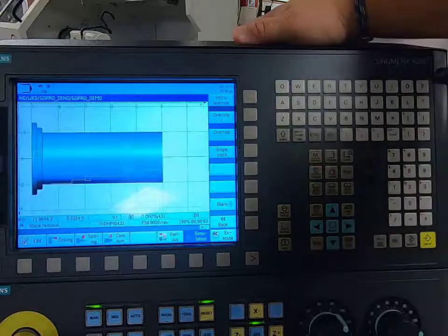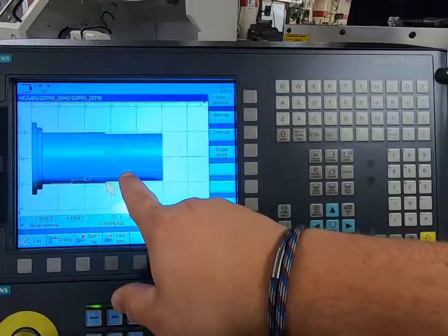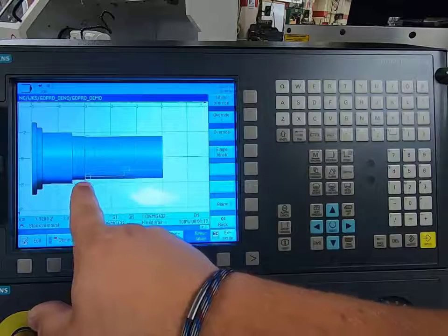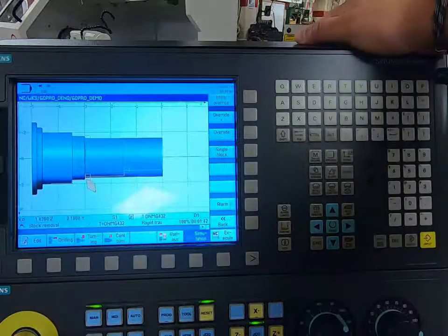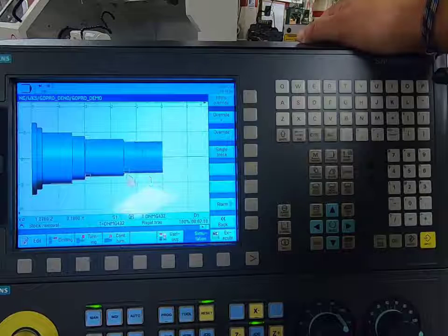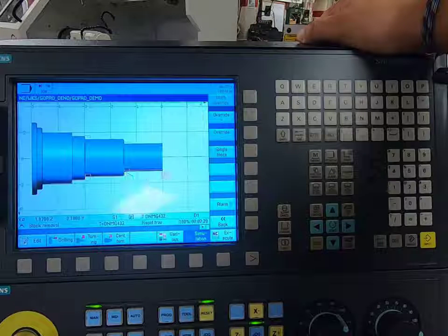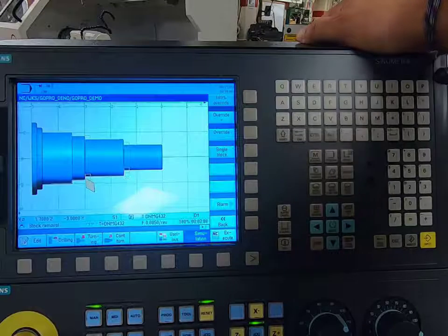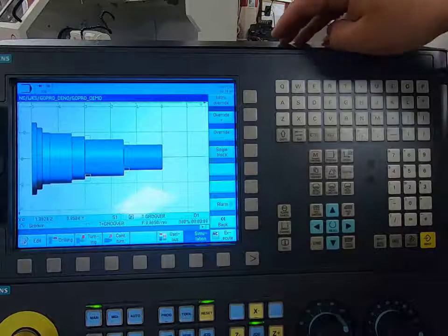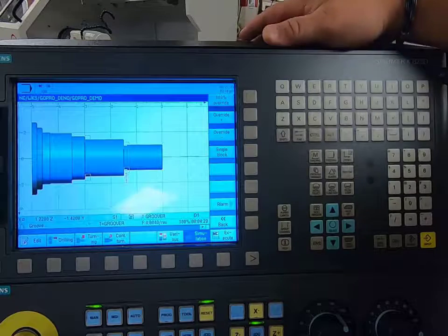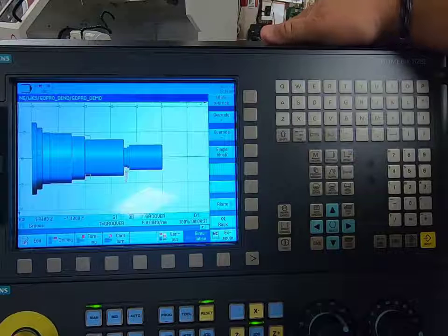So if you look there, my grooving tool is a little bit further in on the shoulder, whereas this one is out past that diameter, so the side of my tool will not run into the face of that shoulder, okay? Now keep in mind, it will cut air for a minute or two. That's not a problem, okay? I say a minute or two, I'm exaggerating. It'll just take maybe about another 10 seconds, okay?